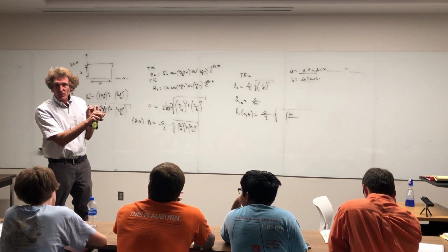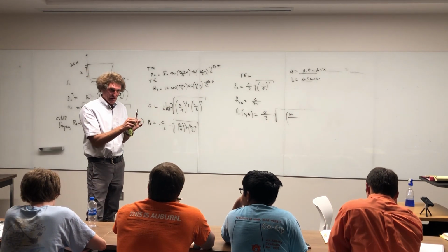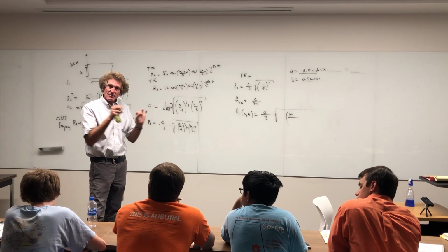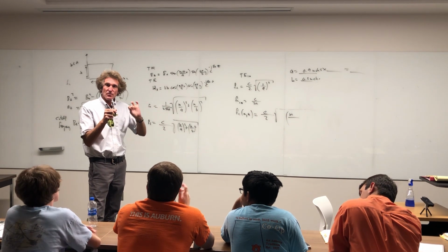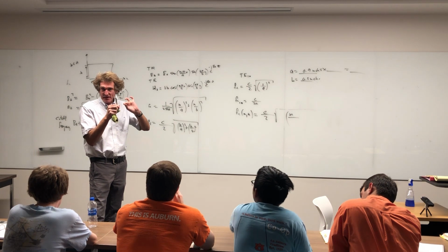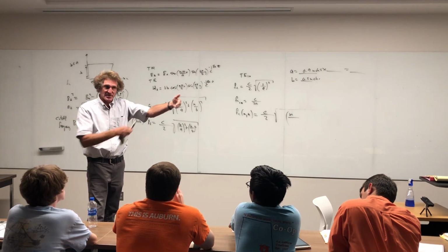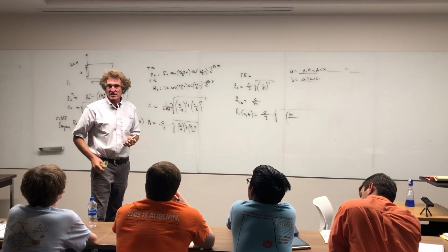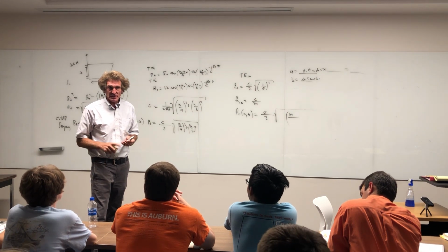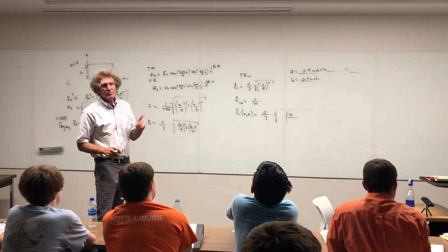If you have energy or power going down, regardless of how much is split, and some of it's moving at C and some of it's moving at, say, 0.5 C, then when it assembles itself at the end, you get garbling if it's a communication signal. You understand that, class? So when you propagate, you only want one mode.